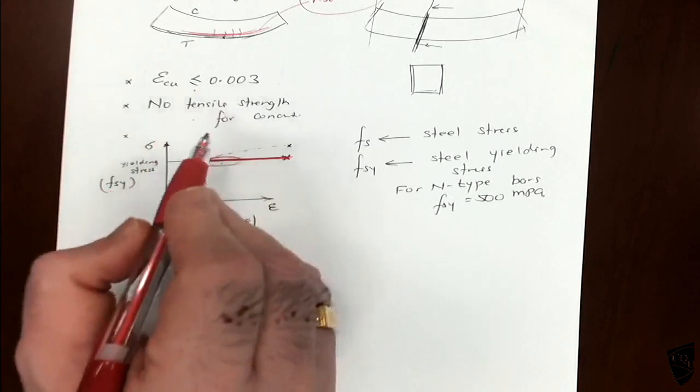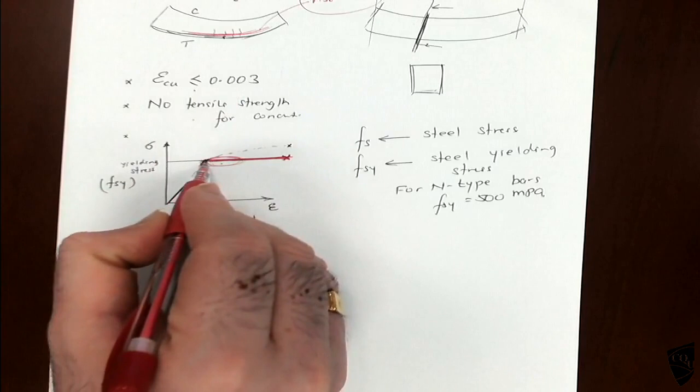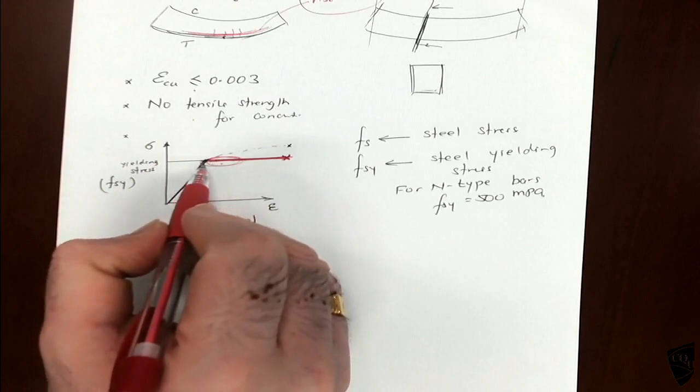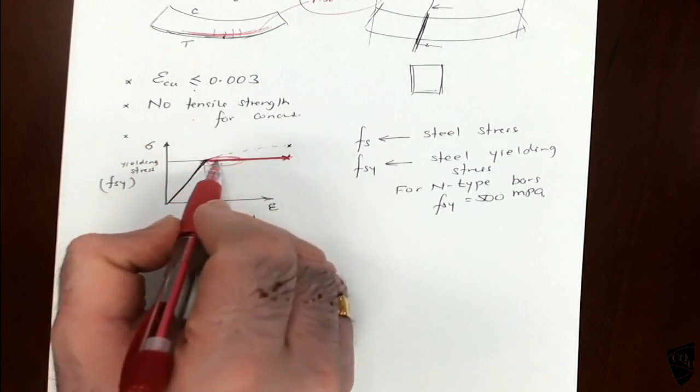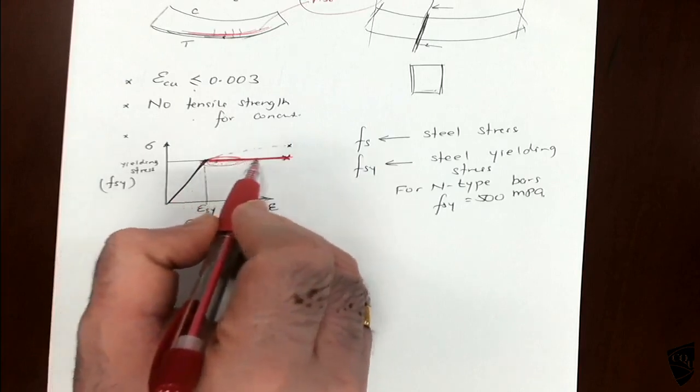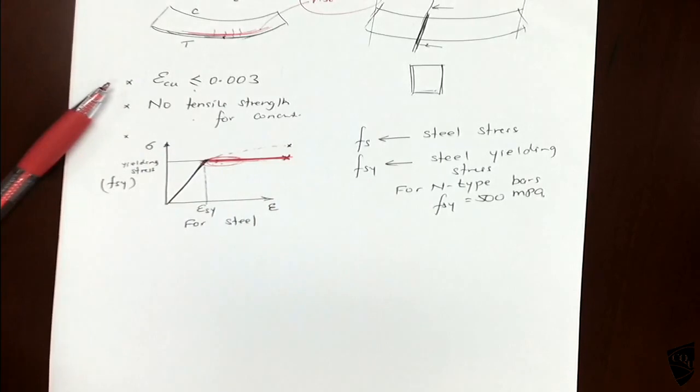The other one is steel has passed the yielding point. Why? We need to make sure they reach the yielding point so that we have enough warning, because in this region steel will expand without any additional force. So if it is already past the yielding point, we will have some kind of warning. Very large deflection or something will show us that it has reached something bad.